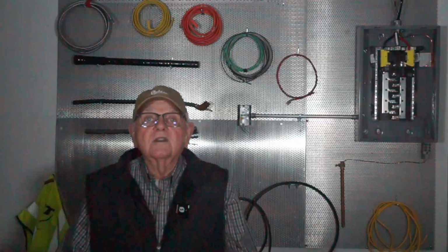So let's talk about the major components in the system. Certainly we have to have a transmitter. What the transmitter is going to do is convert the electrical digital signals into optical or light signals, pulses of light then. The light source could be a diode, it could be an LED, and that modulates the light to encode the data and send it on down the cable. The optical fiber cable itself is the medium, of course, that transmits. So we have the transmitter, we have the cable, and then it's got to go somewhere, right? And so it goes to the receiver on the other end.